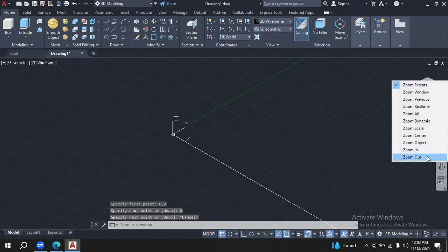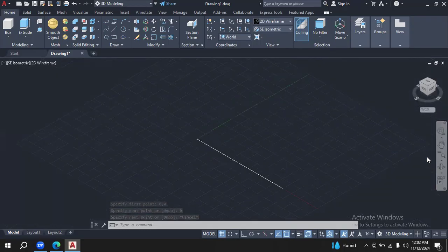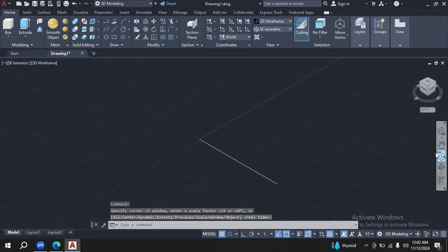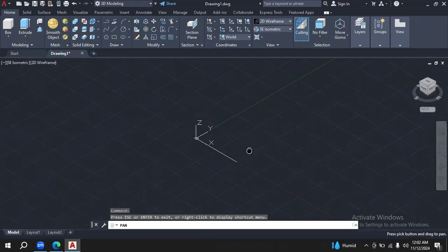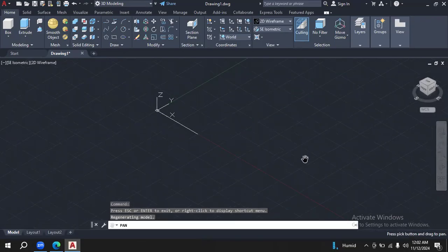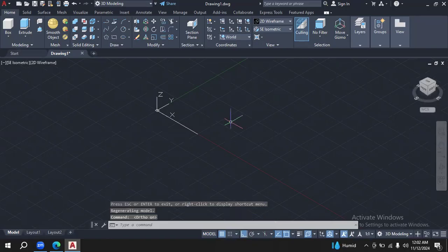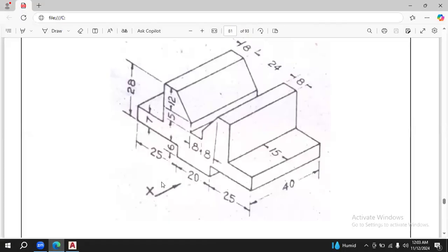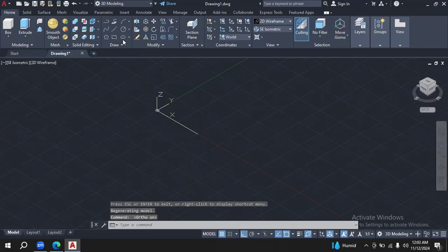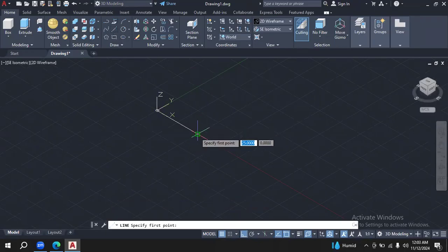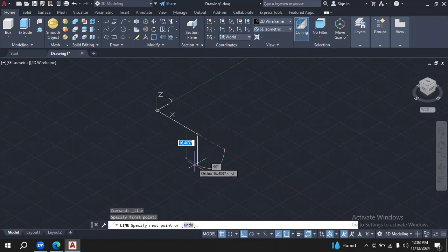First, bring it into your range. So zoom out a little bit more, like this. Okay. Next is to go 6 downward. So again, place your cursor at the end point, press enter, and then go downward by 6. So now it's a negative z-axis as it is showing you here. So just give the length by 6 and enter.